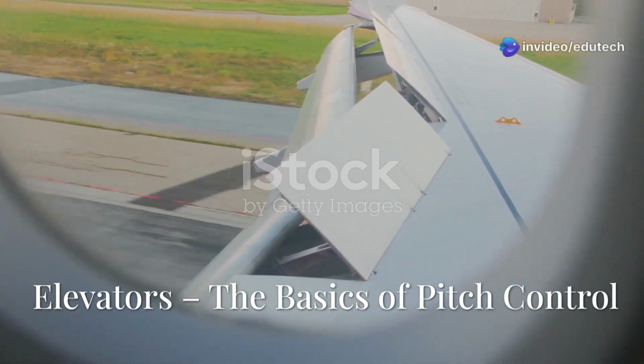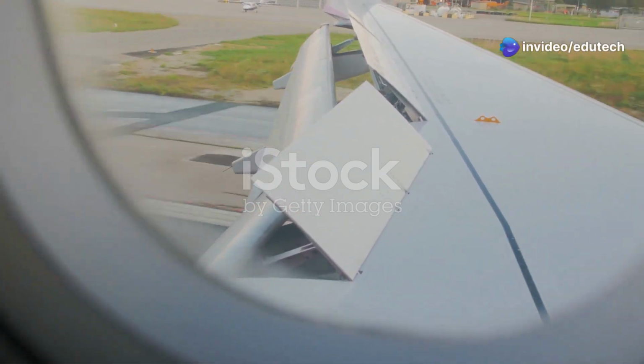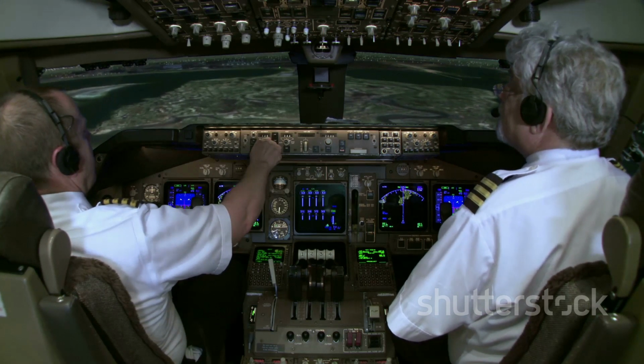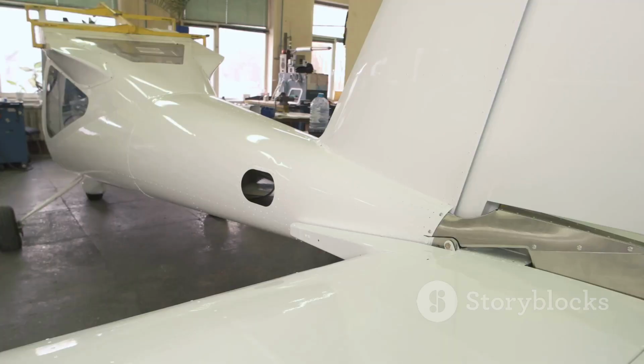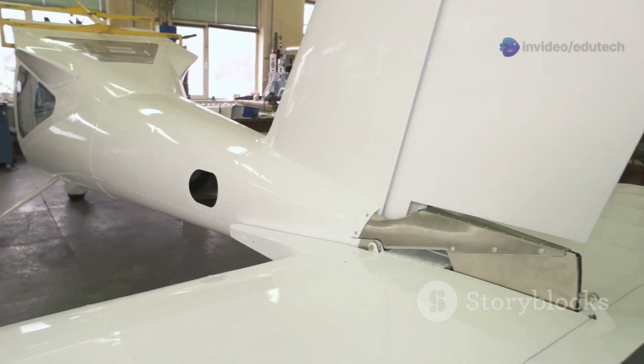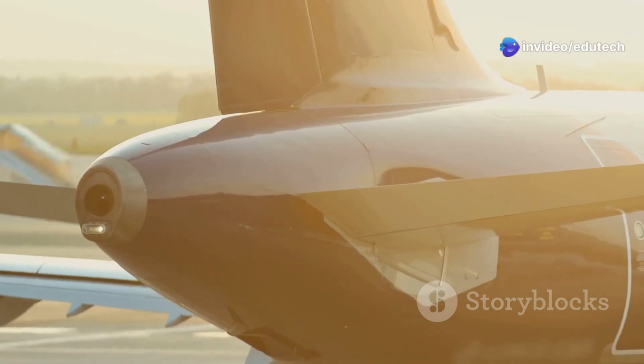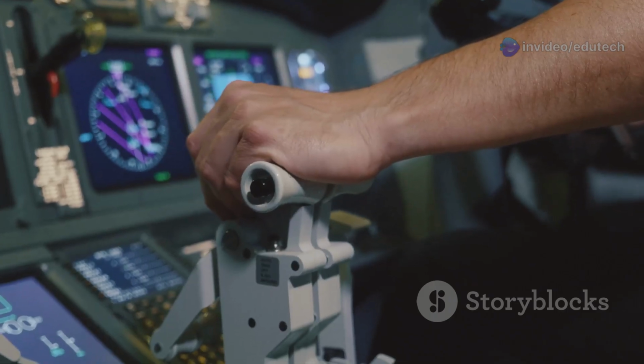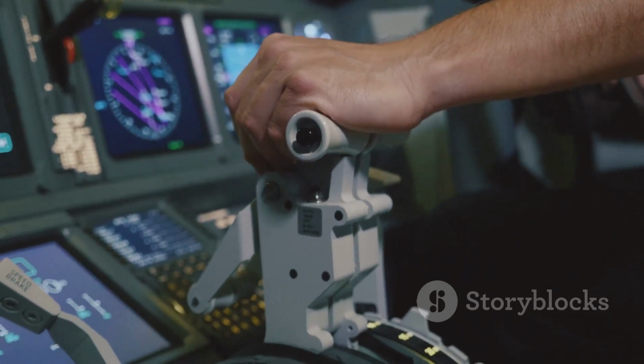So the elevator is actually the primary flight control surface that moves the aircraft around the horizontal or lateral axis. This, in turn, causes the nose of the aircraft to pitch up or down. The elevator is hinged to the trailing edge of the horizontal stabilizer and it typically spans most or all of its width. It's controlled in the cockpit by pushing or pulling the control yoke forward or aft.